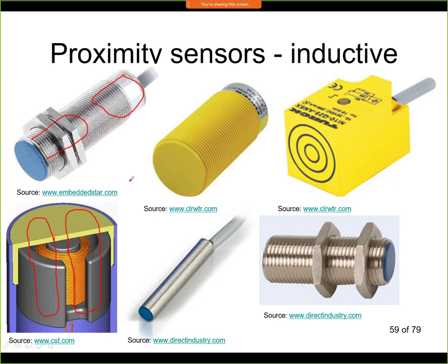The typical range of power supplies in industrial systems is somewhere between 9 to 36 volts. So typically you find the voltage directly written on the sensor. You can see it, for example, here. In this sensor they say it's between 10 to 45 volts, maybe even larger. So it can operate with the industrial voltages. Typically the industrial systems are powered with 24 volts. So it can be 24 volts, it can be 36, something in this area.